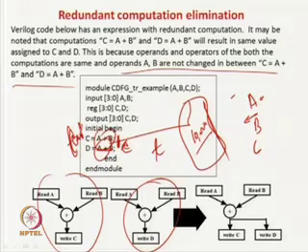But if you are using a temporary variable, then you know that you will not be using it anywhere else, because it is already defined for compiler optimization. So, what happens is that you start with initial begin, then you say temp equal to A plus B, then you know that the value of A plus B is not changed. So, even if the value of C changes anywhere in the code, you are not bothered. So, D equal to temp1, you can write happily, and you will be done with this one.